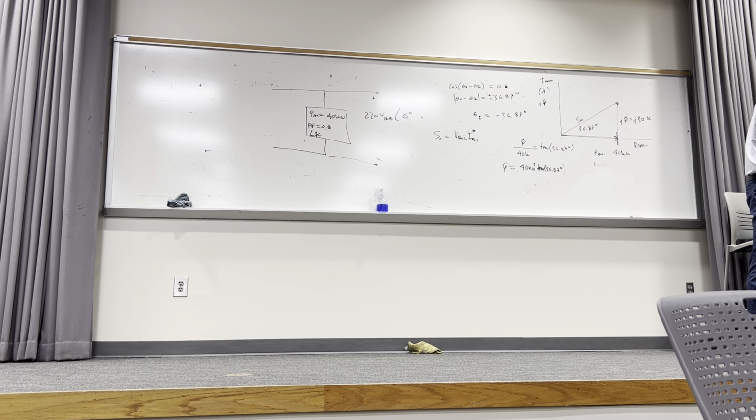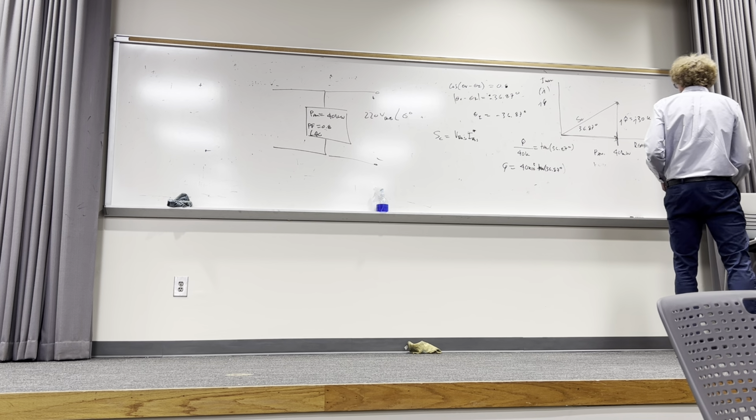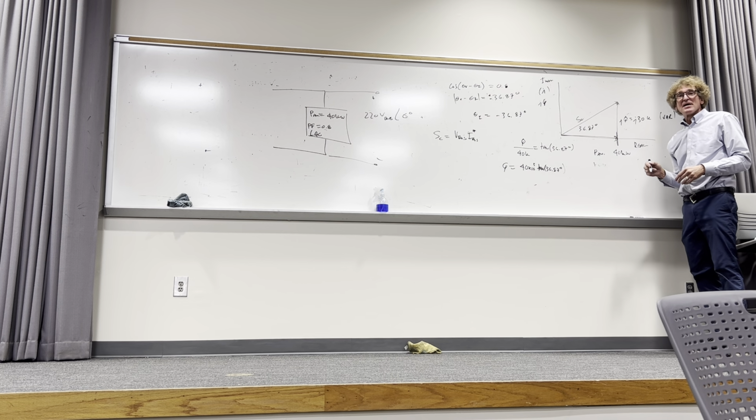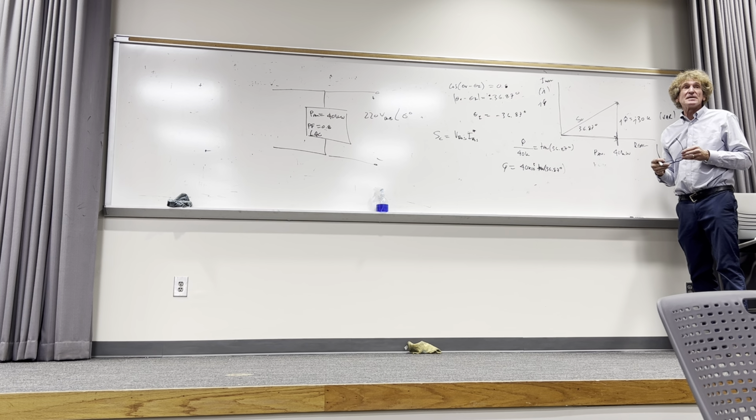And he shows us on page 219, he says the average power is in watts. The complex power should be in VA, and Q, yeah, there it is, in volt amperes reactive, VAR. The units on this one technically are VAR. I'm not going to sting you on this one. Technically, they all have to be the same unit.